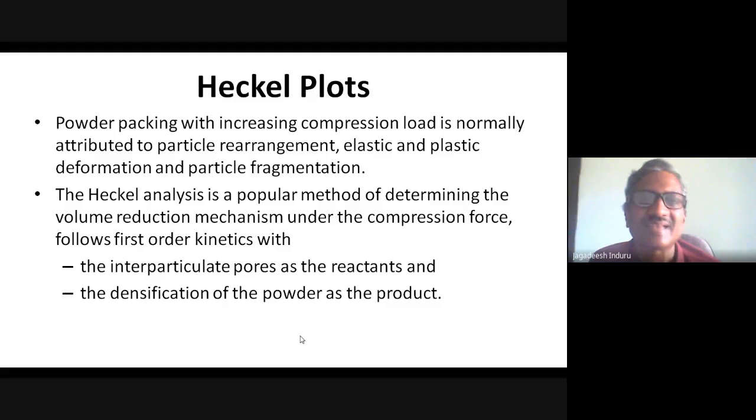It is a size enlargement process. After the size enlargement process is made, if you apply further force, the tablet will tend to get broken, like an impact. When you apply it to any particle, it will get broken. This is called particle fragmentation. Again, the tablet will become a powder. This is the worst stage. You are preparing a tablet and breaking it yourself, so you should not apply force beyond a certain limit.